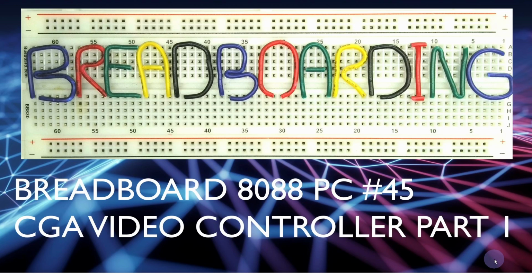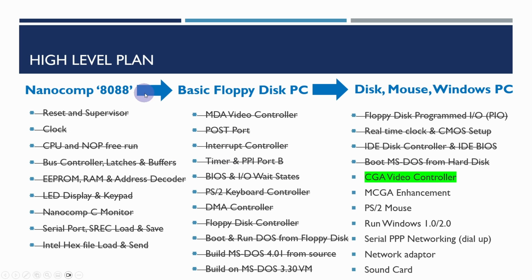Welcome to Breadboarding. This is video 45 in the Breadboard 8088 BC series, and in this video we're going to be looking at the CGA video controller, looking at the introduction to it and high-level design. So this is the overall plan where we've been building out a basic floppy disk PC, and in the previous videos we actually managed to get the Breadboard PC booting off IDE disk controller and configured with an IDE BIOS. So the next series of videos we're going to be building out a CGA Colour Graphics adapter video controller.